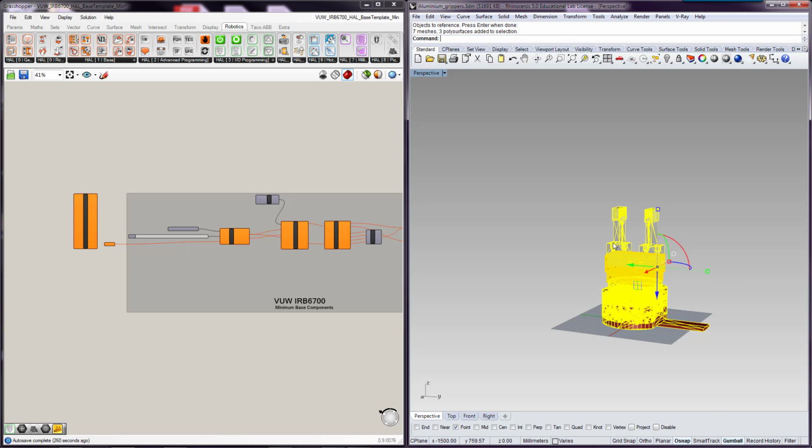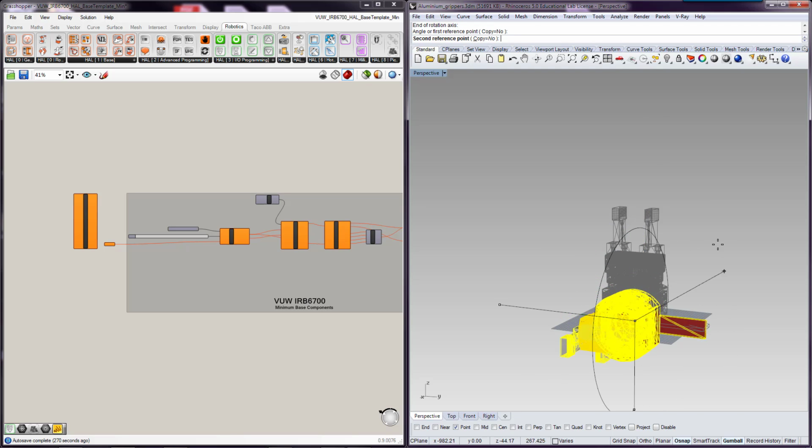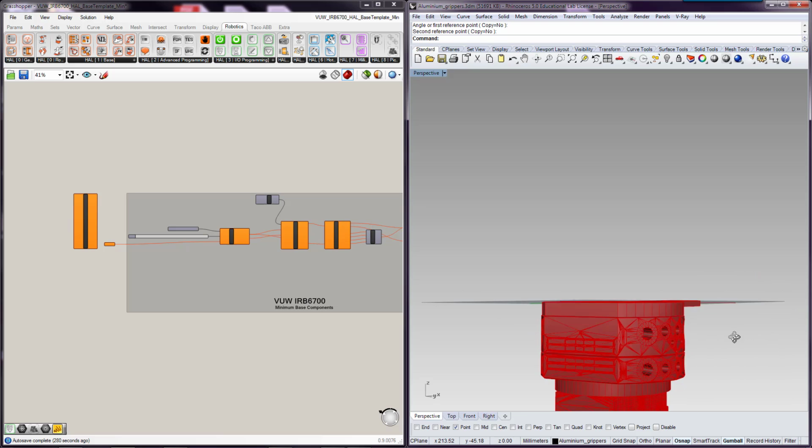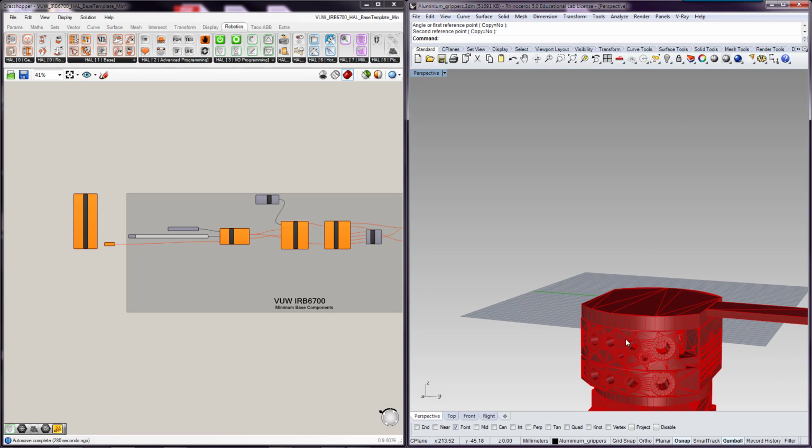So I really need to take all of this geometry and rotate it. I'm going to use a rotate 3D command, start the axis at the center, and just hold down shift and basically lock this thing to a 180 degree movement to just flip it upside down at the origin. So it should be right at the origin still, and we should have all of our parts.